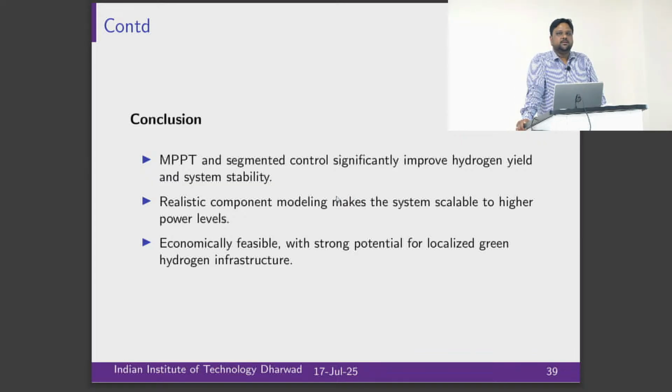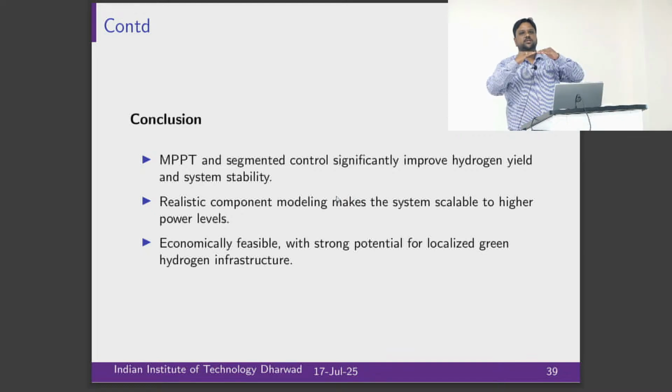Another important characteristic is that a hydrogen electrolyzer is a low voltage, high current device. But a battery you can still operate with a normal DC voltage. So even if they share the same DC bus, which is compatible with the battery, you might require another stage of DC-DC step down to feed the electrolyzer.